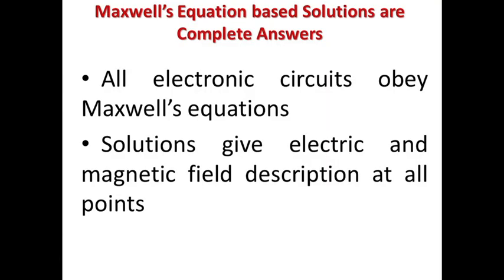But at higher frequency, obviously that is not the case. There we need to consider the non-TEM type of propagation. Maxwell's equations get solved there by various modes, that is why power gets transported by various modes, and we will have to solve those problems with the help of Maxwell's equations and boundary conditions.